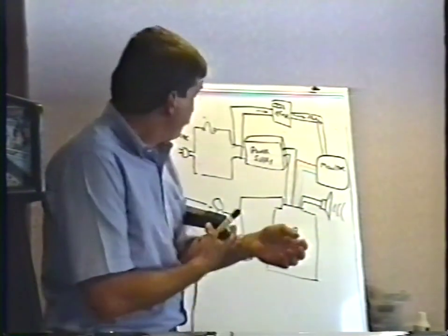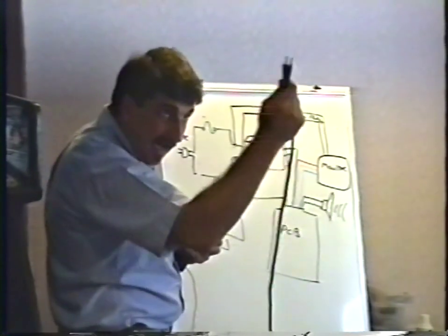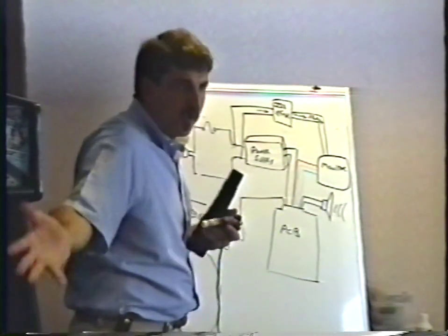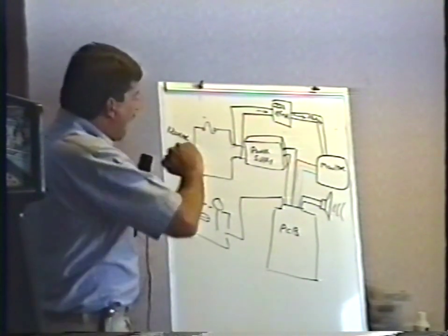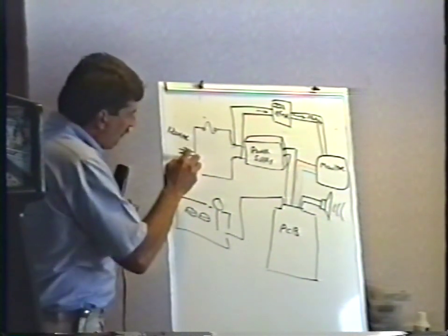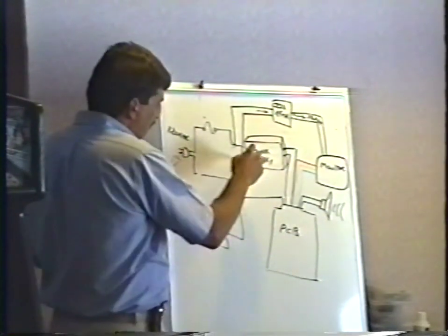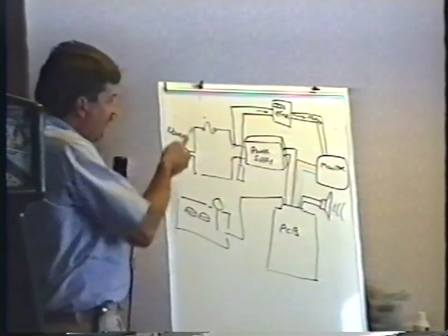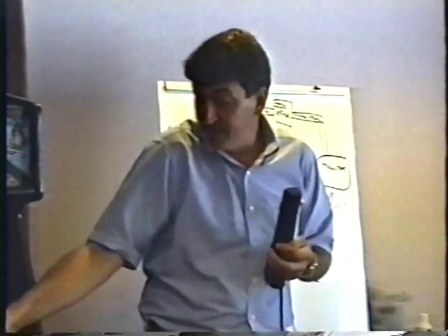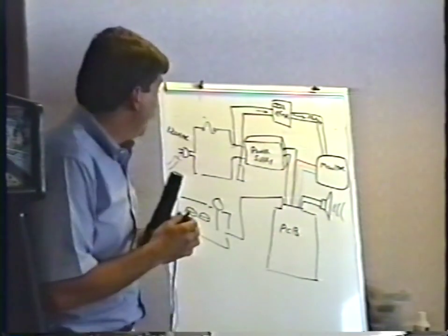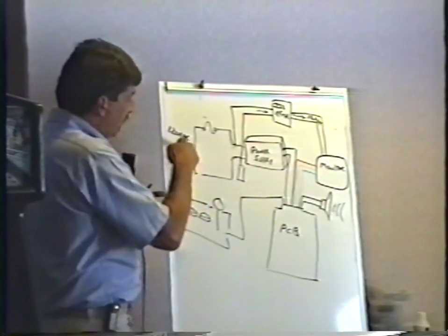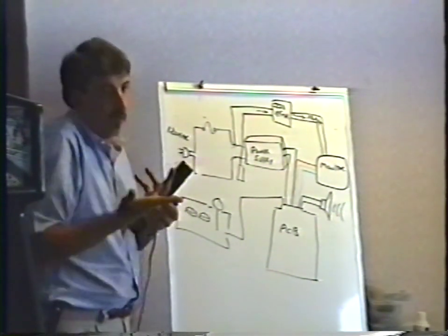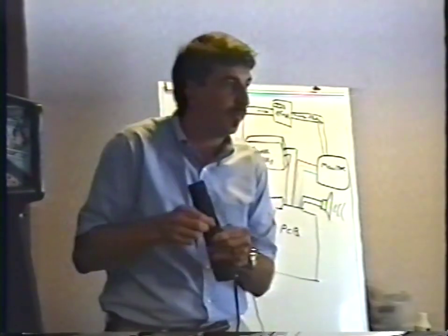Next step then is, with this thing out, disconnected in my hand, not plugged into the wall, I use my meter on the ohms scale, the continuity scale, like the 200 ohm scale or whatever beeps on your meter, and I start by putting one meter lead on one of the prongs and the other meter lead on one of the wires here, or I put one meter lead on a wire here and then just try each of the two prongs. What I'm checking for there is continuity. In this case, when I put one meter lead here and one meter lead on this top prong, it beeps. That wire's good, but when I move to the other one I don't get a beep. One of the wires is broken, and it's really probably the plug.